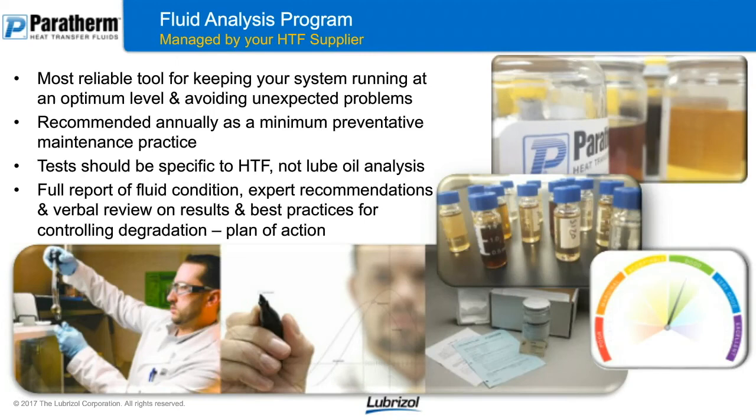But you could have some serious flow issues. You could have some serious degradation blocking lines. If you have cold spots or you're seeing inefficient temperature out of your heater, get a fluid analysis done. You'll be able to determine what the problem is and fix the problem right ahead.